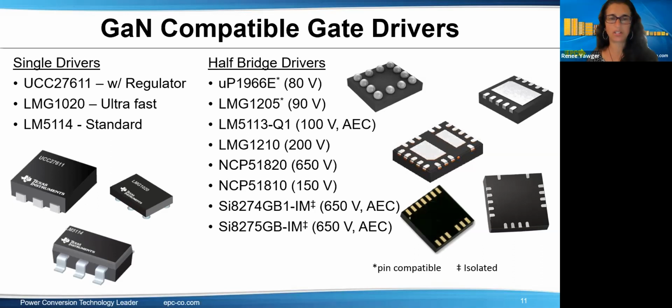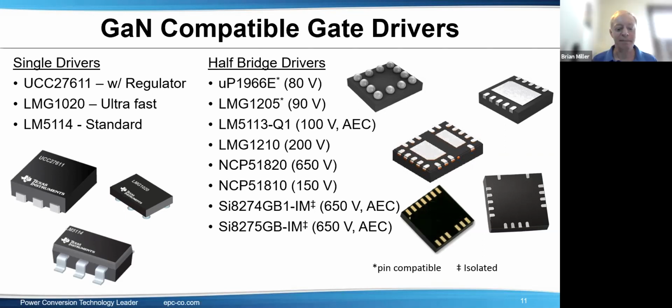Do you have any recommendations when approaching the limits of the gate driver? How can one stress test the gate driver? I think one way to look at that is the ringing on the gate driver. A lot of them specify, for example, if you take one here, it says 80 volts. Looking into the absolute max is 80 volts. Also the limit for the switch node plus the gate drive top. So looking at the different nodes would be good to see just how far you really are stressing it.